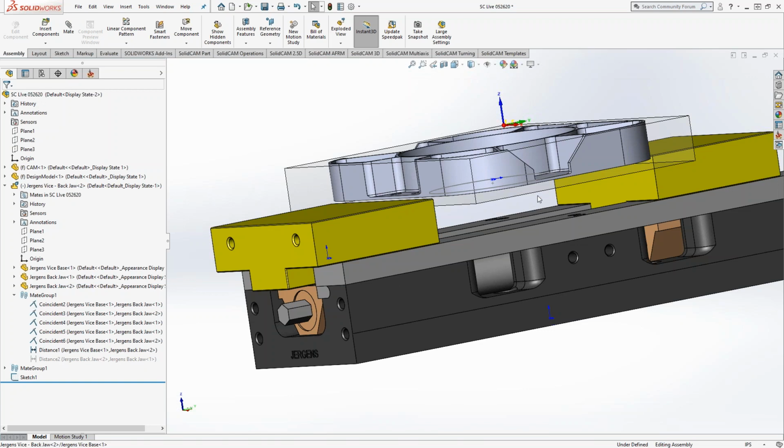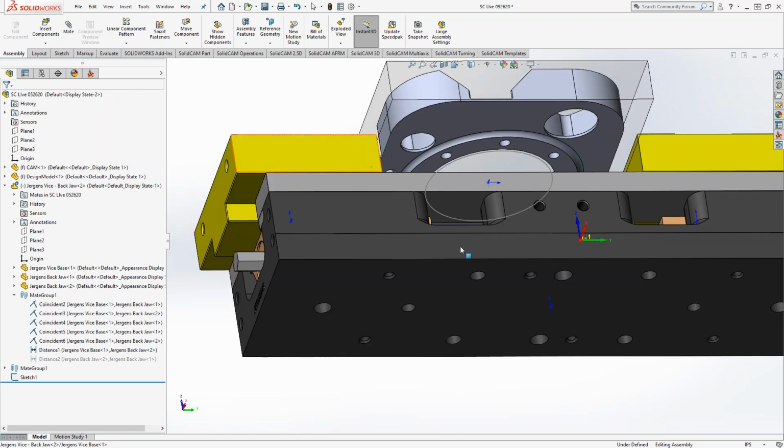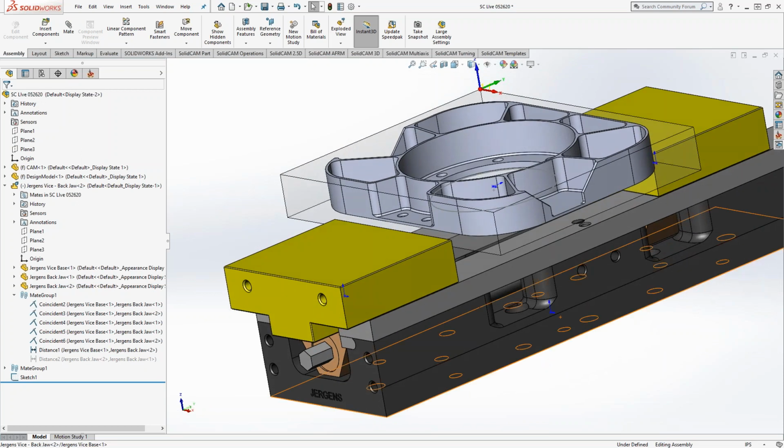So there's always that same thing of you can skip a couple of steps if you just keep in mind what it is that you're skipping over. But absolutely, I would say just these guys here is all I need for fixture protection. But when I go to set this thing up in machine setup, I'm going to take advantage of the fact that I have the solid here and get the bottom center of this face to be my fixture mounting coordinate system. But let's see. Jake also has a question here.